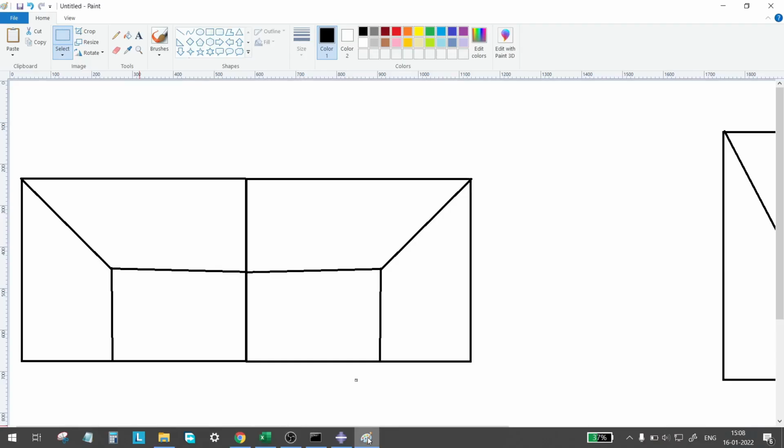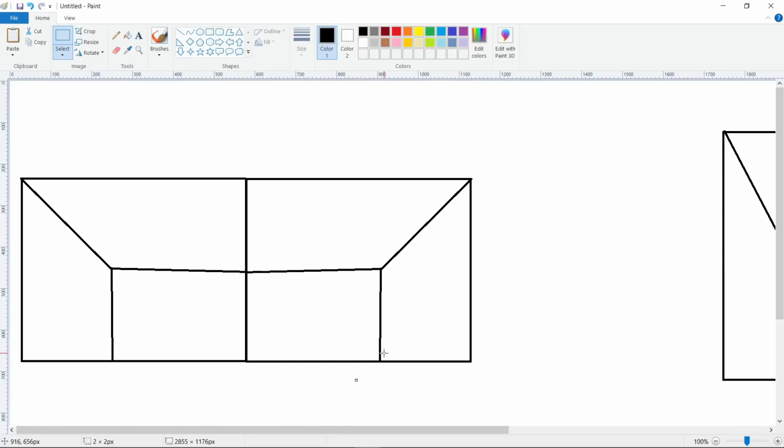Hello friends, now I'm going to show you how to create a transition meshing in Abaqus. So first of all, why do we need transition meshes? When we need finer meshing in the area where we need to focus our attention, such as high stresses or